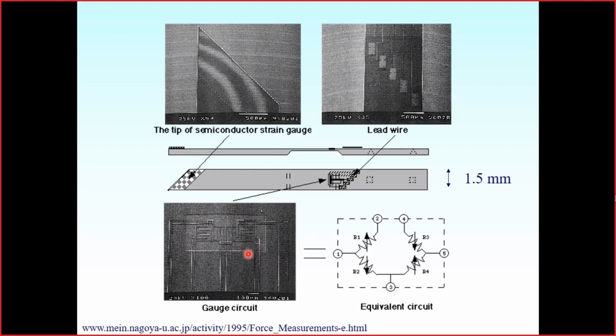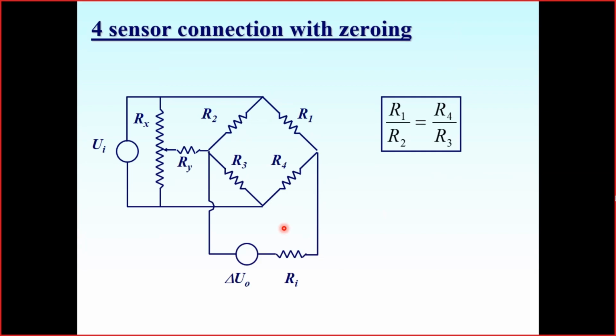Working together, they provide very excellent sensitivity of the bridge circuit. The most important thing here is to switch them correctly. Those elements which increase the sensitivity when the outer excitation occurs should be connected in the opposite branches. And so should the other pair of the sensors, which are oriented in parallel to the cantilever, to the object axis.